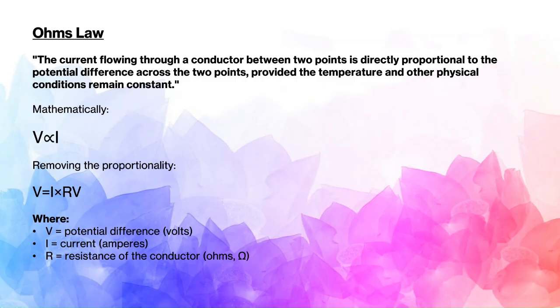The thing is that you may have seen even in your career that many people really don't understand this. And if you ask what is Ohm's law, they will simply say it is V equal to IR. But my understanding is, if you really want to be a good engineer, you need to understand this law inside and out. So the first thing is, this law is applicable for a linear circuit.